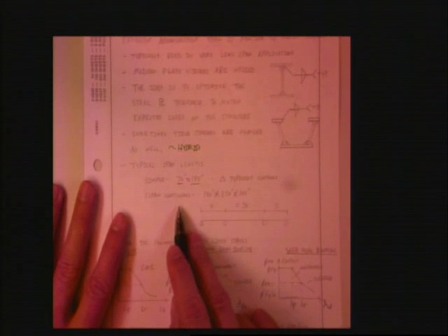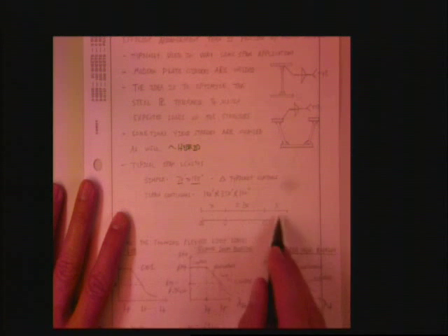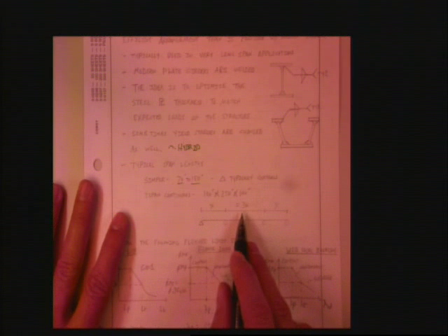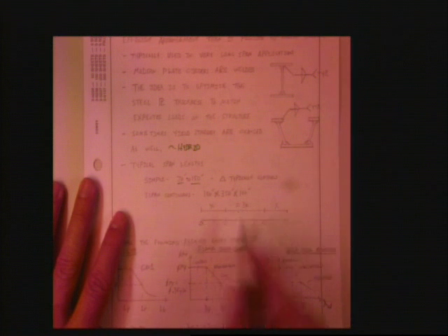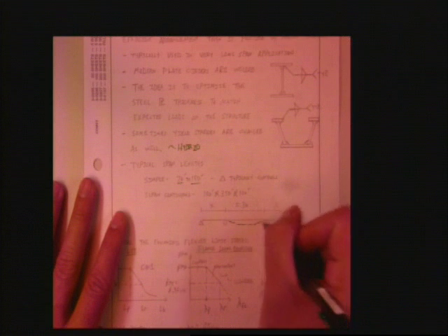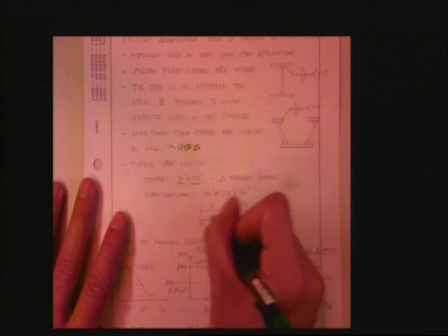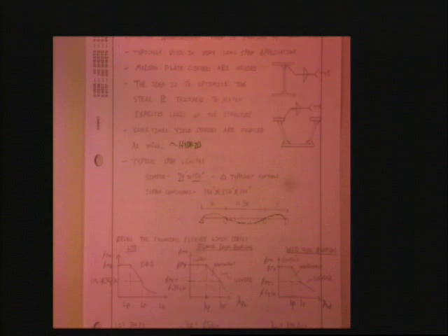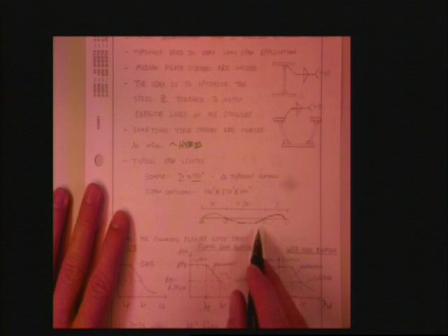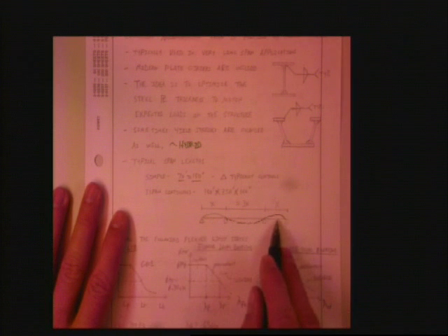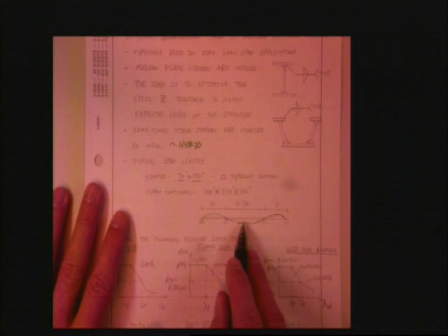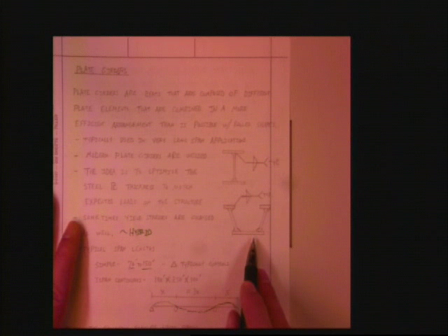A 3-span continuous girder usually has something like the first span maybe 100, the last span maybe 100, and the middle span in the realm of 300 and some change. They do this on purpose to balance deflection, because as the middle goes down, the ends go up. So we're talking about a continuous girder. Obviously you wouldn't ship a 500-foot long girder out to the site. It would have splices in it. They may come in shippable sections. This may be 2 sections, this may be 2 sections, this may be 3 sections. Sometimes when you get really shallow, you have to go to tub girder type shapes. There's your plate girders.